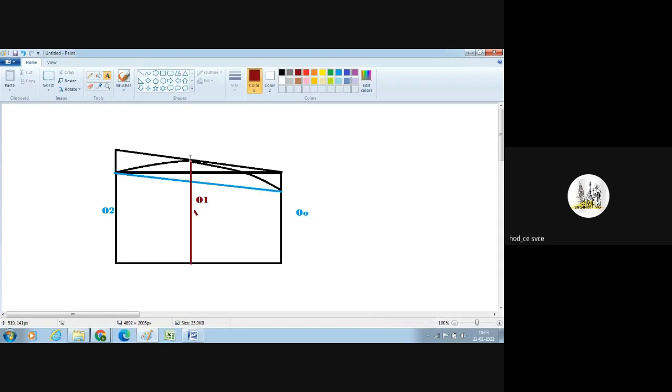This is F, as you know we have already integrated, and this is H, right? FH multiplied with the distance of A to B, that means the horizontal distance. Generally, what is the formula for the area of a triangle? Half into base into height. Instead of that, for the area of this parabolic segment we calculate 2/3 multiplied by its height and base, right?